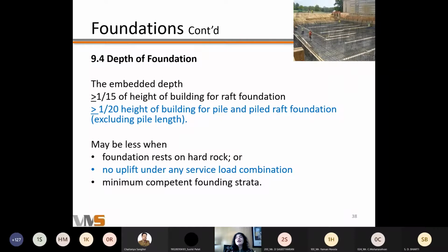And you do need, see, as I showed right in the beginning, you do have toppling of these very rarely. Very rarely have you seen toppling, but in an 8.8 earthquake, anything which is 8 plus magnitude, there is a possibility of these things, and as I said, these are affected by the short frequency component of the seismic waves, right? So you want to make sure that you're quite safe for toppling or for rocking, for that matter.